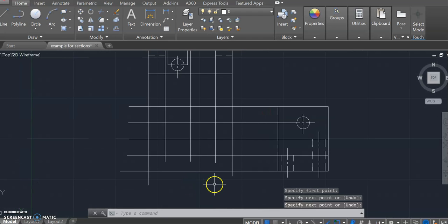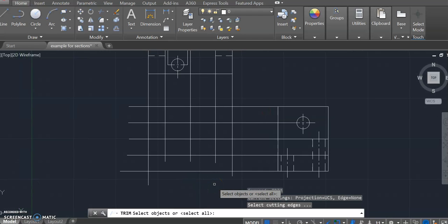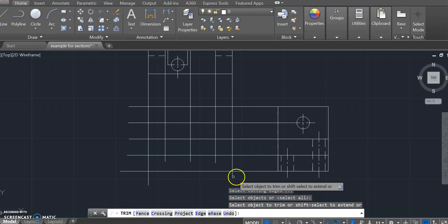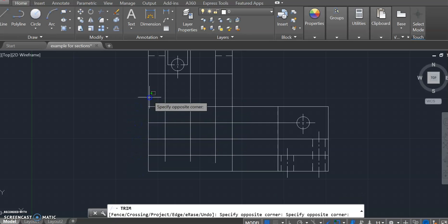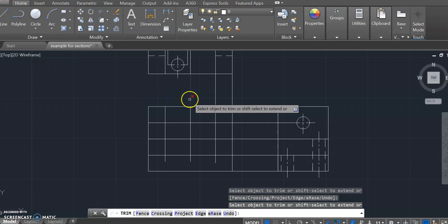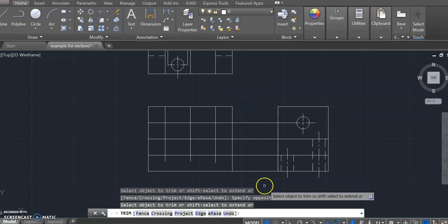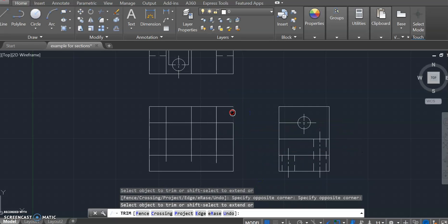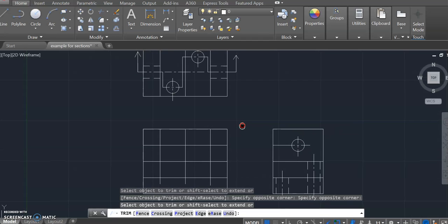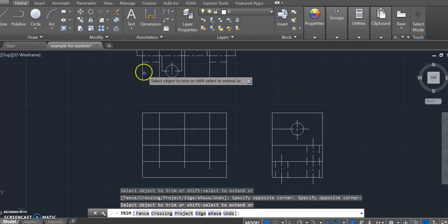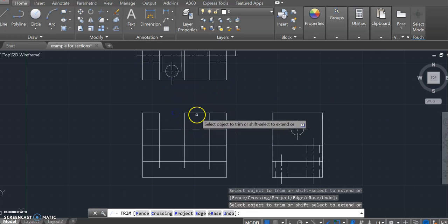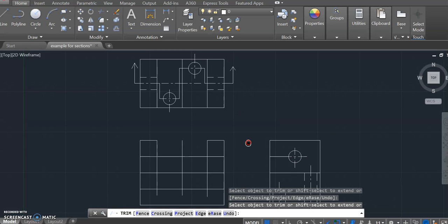Okay, so what I'm going to do is use my trimming tool to just clean this up a bit. And this is going to allow me just to select the pieces that I don't need and get rid of them, and just make a very nice outline for the entire part. So continuing on, just to see what I'm trimming here, this tall surface is going to occur on either side. So I can really get rid of what's happening in the middle there. Okay.